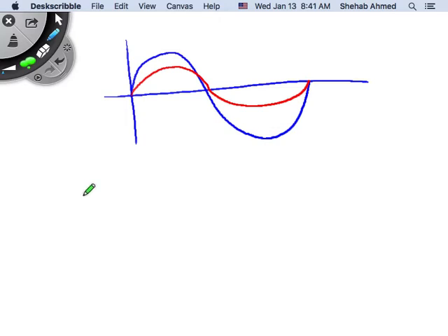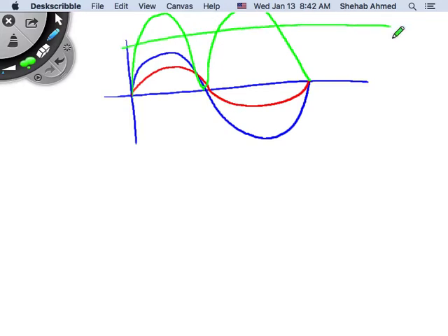Sinusoidal? Yeah, it's a multiplication. But is instantaneous power going to be sinusoidal? No. You're multiplying these two by each other. It will look something like this, for example. How about if you multiply these two by each other? It will look like this again. Right? So this is power. So power in single phase is pulsating. Right? This does have an average value, right? So you can get some real power out of it. And we'll review real power equations later, but it's a pulsating waveform.